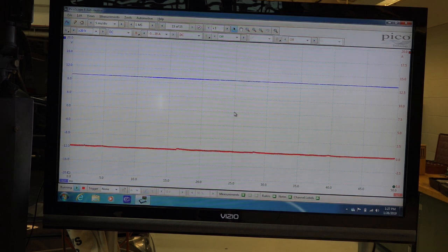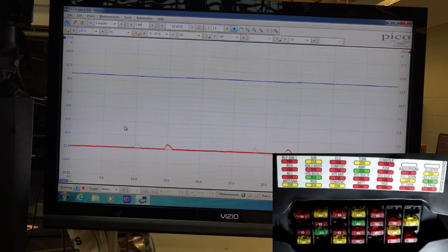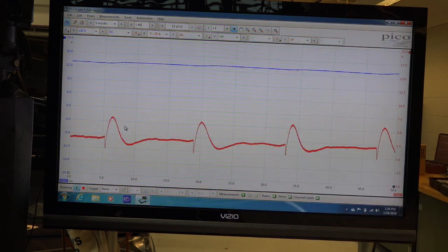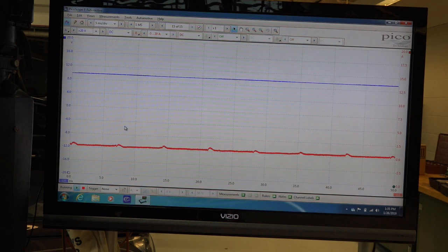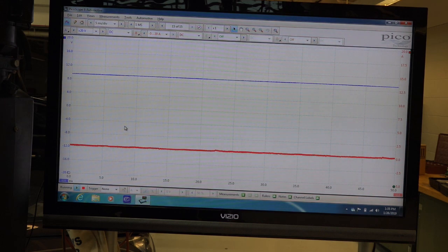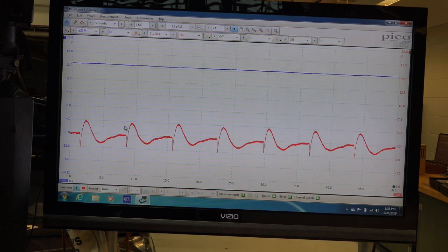So I'm going to go back and attempt to pull that fuse. It appears to still be pulsing somewhat. Oh, there it goes. We're still climbing up over 10, probably 11 or better amps. All right, so I'm going to look more at the blower motor as the culprit here. I think I will go ahead and just disconnect the blower speed wire here at the blower motor. We'll just depin it from the connector and see if we still get this going on.